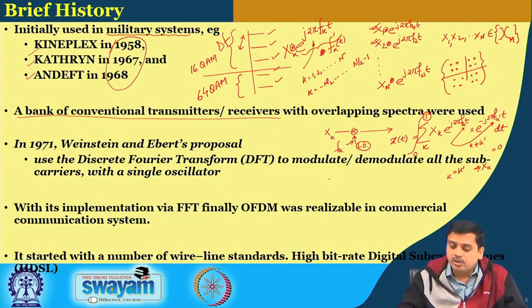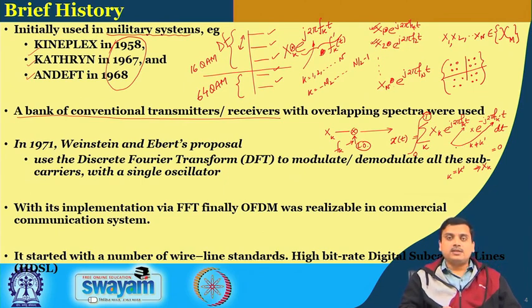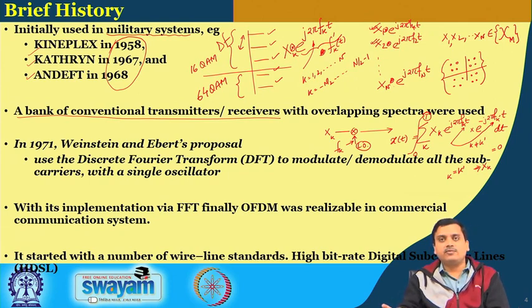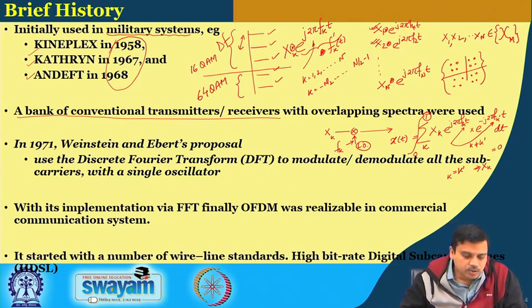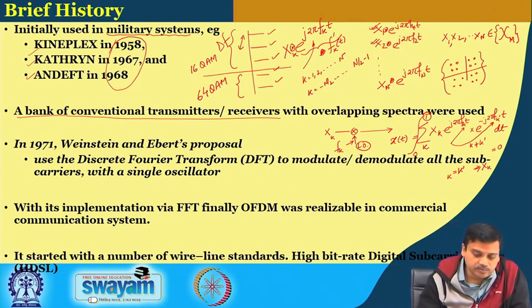So, essentially it turns out to be a correlator receiver, because finally you will be sampling at this time instant t. So, one can also visualize this in terms of n dimensional signal with n basis functions and a matched filter operation at the receiver with the particular basis function. So, we project the incoming signal on the different basis functions, read the outputs and then process it further. So, if you see it in this way, then it is a generic representation, you can study all the schemes in one particular platform.